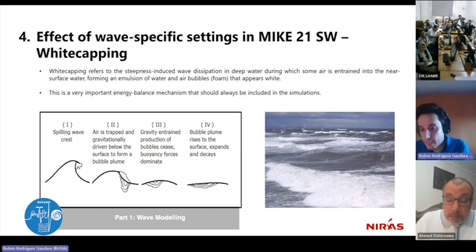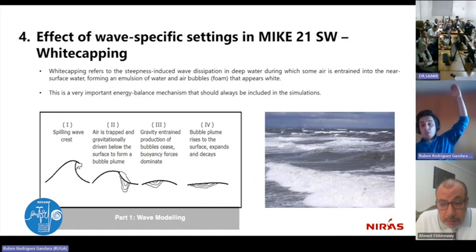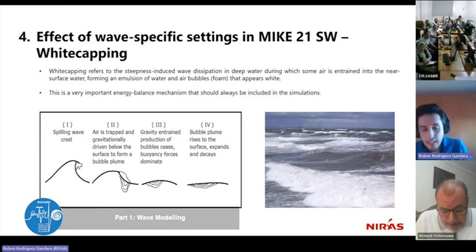The same way that shoaling and breaking control what happens to the waves near shore, and breaking happens because there is little water depth and the waves shoal until they get to a limit where they have to break, in deep water you don't have that limitation. In deep water, we said that the waves do not feel the bottom. The bottom is so far from the surface that waves cannot break due to the bottom. But if you go on board a vessel and you have been unlucky enough to go on a cruise and have to cross a difficult sea or a storm, you see that waves are still breaking in the middle of the ocean.